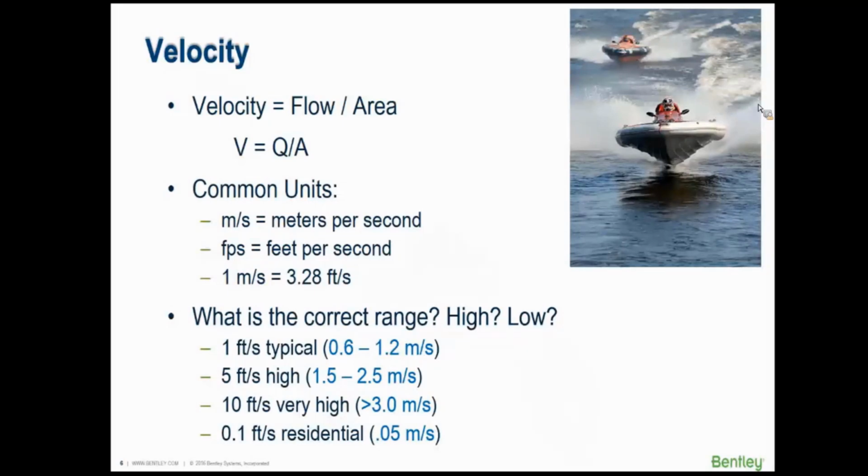Another problem when you get really high velocities, and we're not going to cover this in this course, is that we could have a lot more problems with hydraulic transients when you change the velocity. So with high velocity, you could get hydraulic transients, which are water hammer events that can burst pipes if you're not careful about them. So we tend to stay away from those really high velocities, partly for energy, partly for transient reasons.